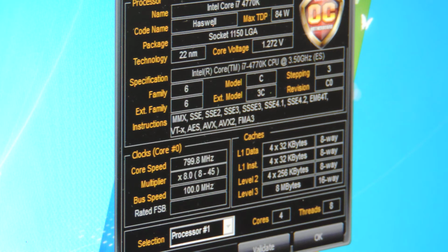48X. You saw that, right? Now press one more time, and this should go at 49X. Yep, back down again. Now we should go to 50X. So I can change the multiplier without actually changing the multiplier. In real time, I can change it, and the system knows to change it, and now I should go to 50X when I re-engage trigger. Yep, 50X. So I went to 5 gigahertz on the same voltage.